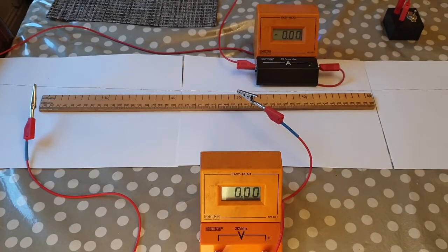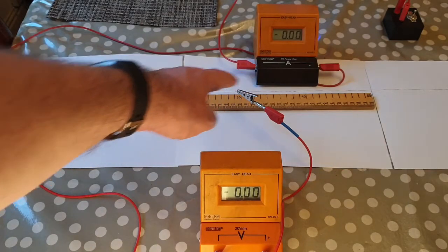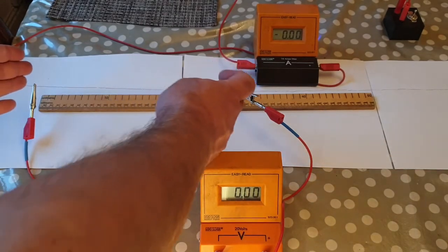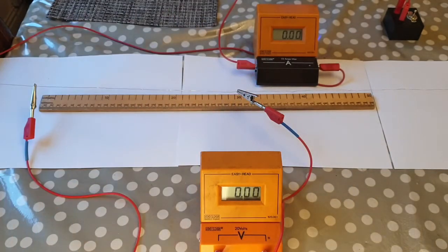Well, number one, the length of the wire. Now this should be fairly obvious, because if I double the length of this wire, and I've sectioned off a 30 centimetre length of copper wire here, if I was to double that to 60 centimetres, that would be like having two equivalent resistors, one after another, in series with each other. The resistance would add up, so it would end up having twice the resistance. So the resistance of a wire must be directly proportional to the length of the wire.